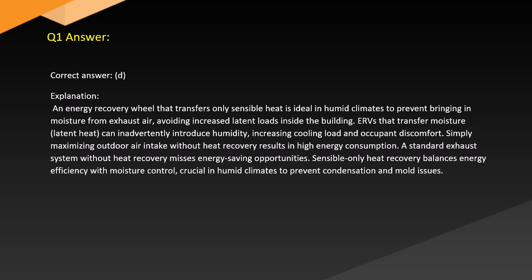Simply maximizing outdoor air intake without heat recovery results in high energy consumption. A standard exhaust system without heat recovery misses energy-saving opportunities. Sensible-only heat recovery balances energy efficiency with moisture control, crucial in humid climates to prevent condensation and mold issues.